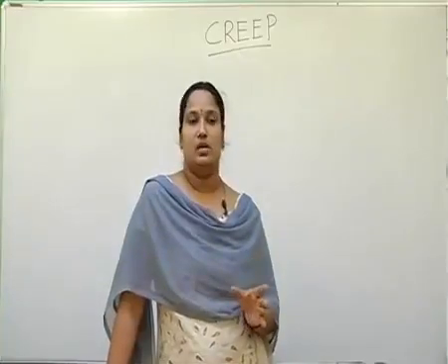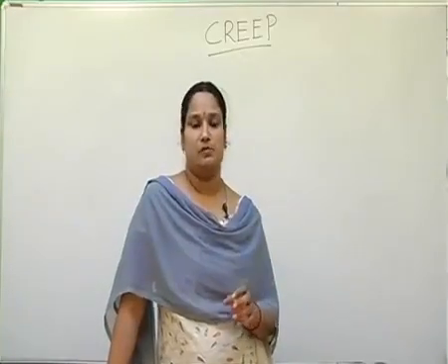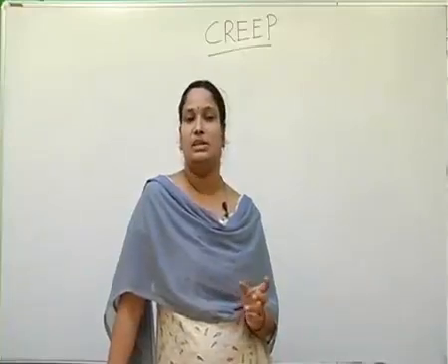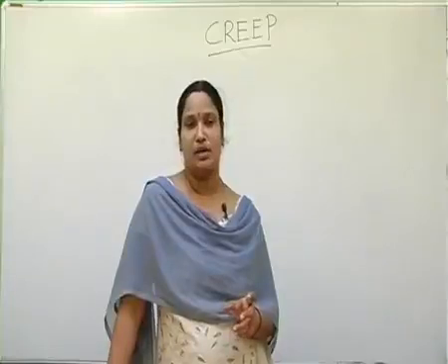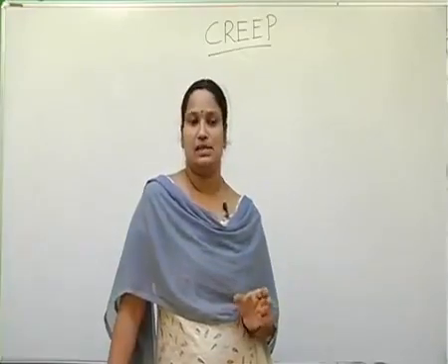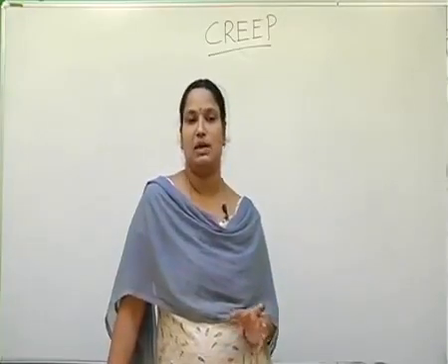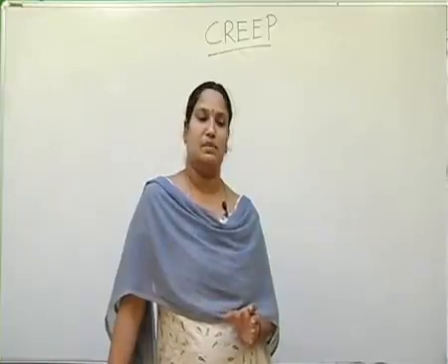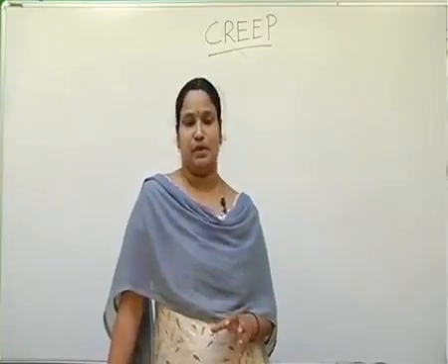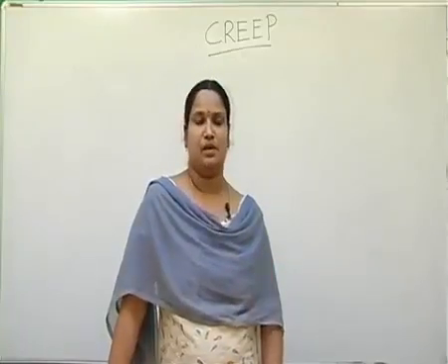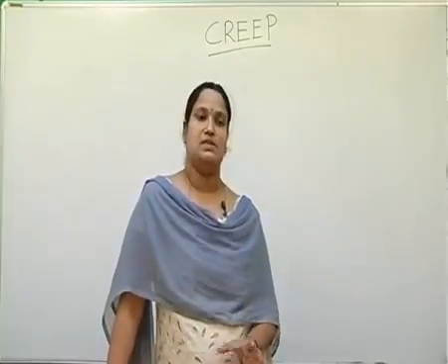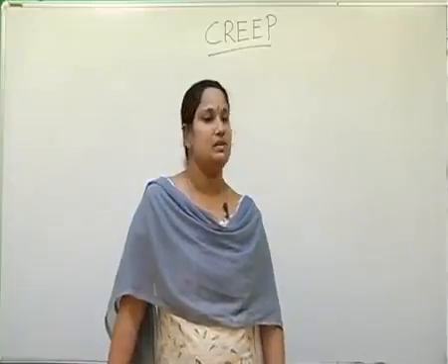One involves lattice diffusion, and the other, Coble creep, involves grain boundary diffusion. Coble creep occurs at lower temperatures when compared to Nabarro-Herring creep, and grain boundary sliding takes place at very high temperatures. So these deformation mechanisms have also been discussed.